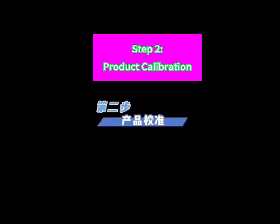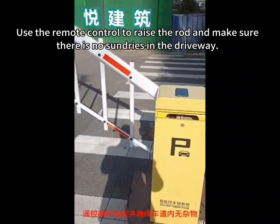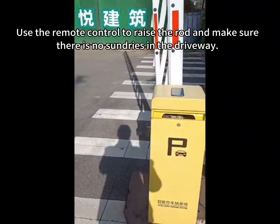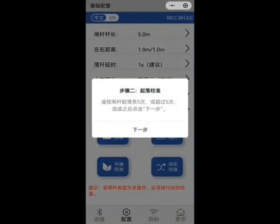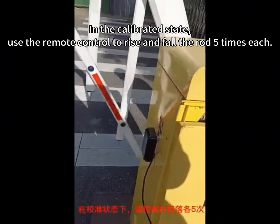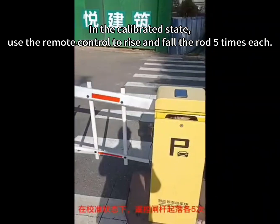Step 2. Product calibration. Item 1. Dynamic calibration. Use the remote control to raise the rod and make sure there is no sundries in the driveway. Click the Dynamic Calibration button in the applet. In the calibrated state, use the remote control to raise and lower the rod 5 times each.